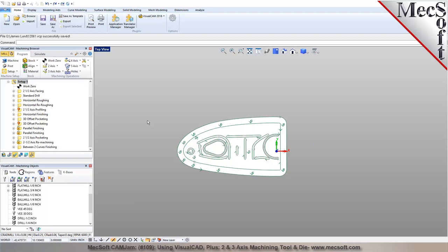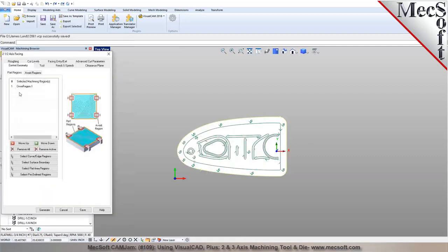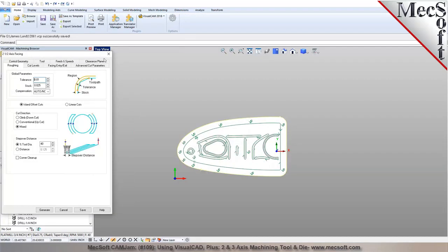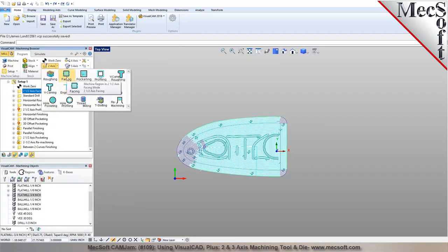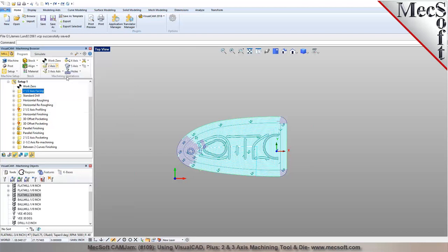So on these operations, when the next time I open that dialog, do they have default values or do they just retain what you did last time? If you edit one of these, it'll have the values that you put in. If you start out a new operation, it'll load from a default, whatever is the factory default setting. However, you can customize and set your default.